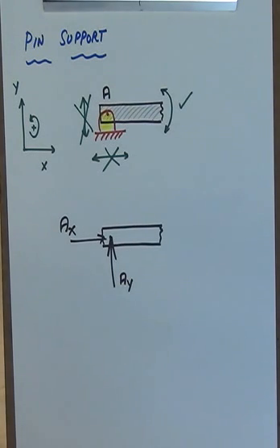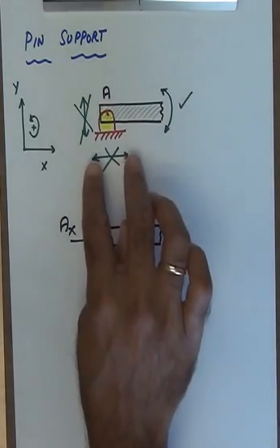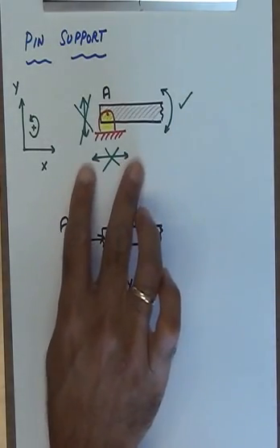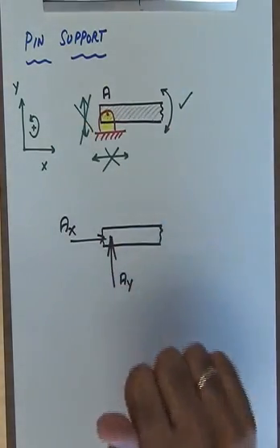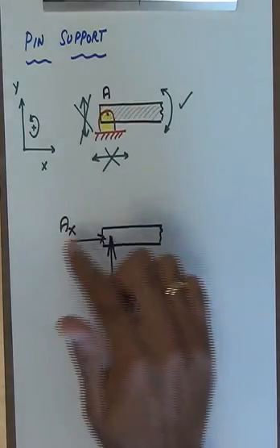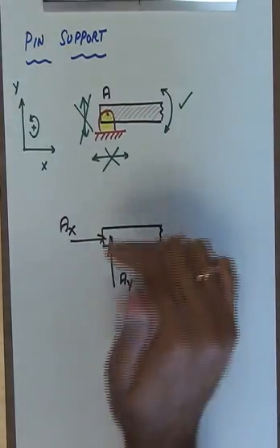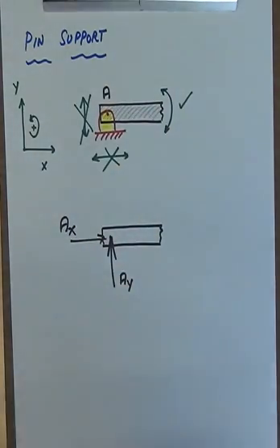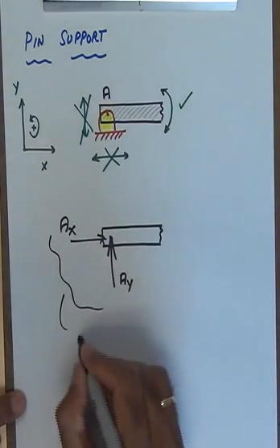And the basic idea is that on the free body diagram we draw the effect of the pin by showing what constraints the pin produces on the rigid body, and the only constraint the pin produces here is that it does not allow me to translate along the x-axis, neither does it allow me to translate along the y-axis. And so I'm going to have these as the forces of constraint on the rigid body, and these will be the pin reactions.